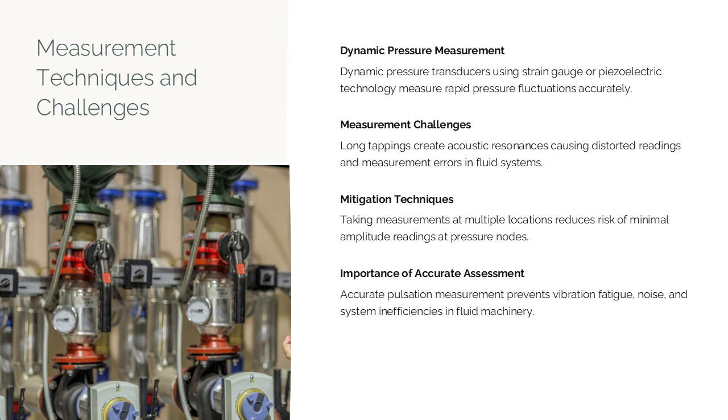Despite these precautions, limited measurement points may still fail to represent maximum pulsation levels due to standing wave patterns in the fluid. Industry standards provide pulsation criteria for specific applications, but engineers must interpret results carefully to ensure accurate assessments. Effective pulsation measurement helps prevent issues such as vibration-induced fatigue, noise, and system inefficiencies.